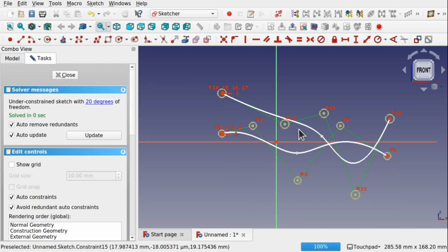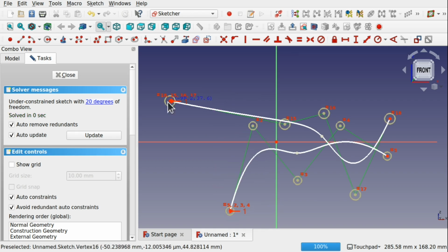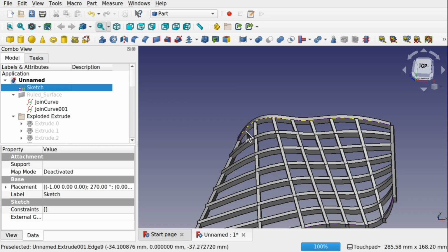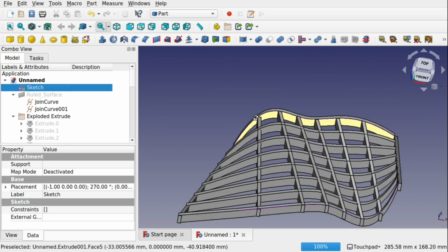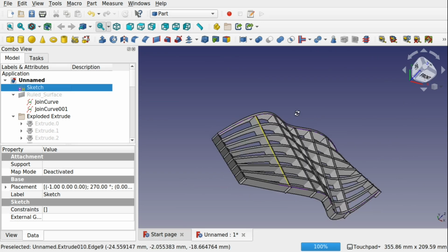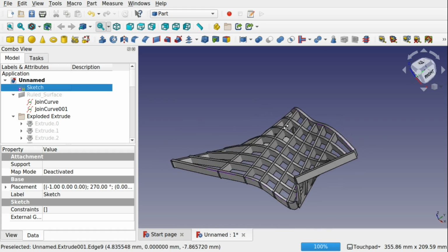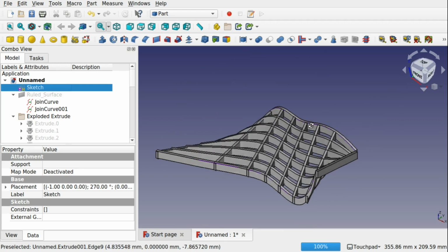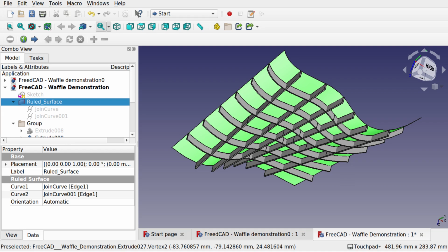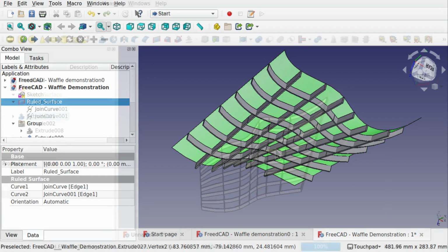Come into the sketch and move the sketch and hit close. You can see that's moved as well. So we've maintained the parametric abilities of that sketch. We're going to look at another way of doing this in the Curves Workbench, but using the ISO curve along with the split curve together to make those extrudes.